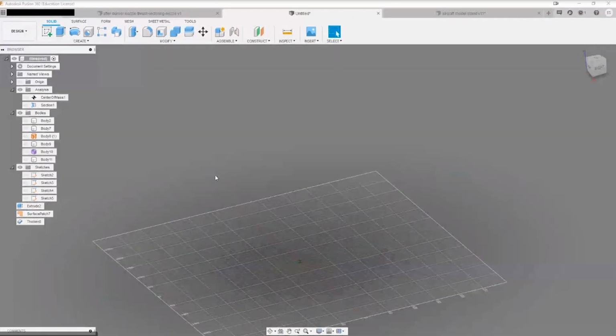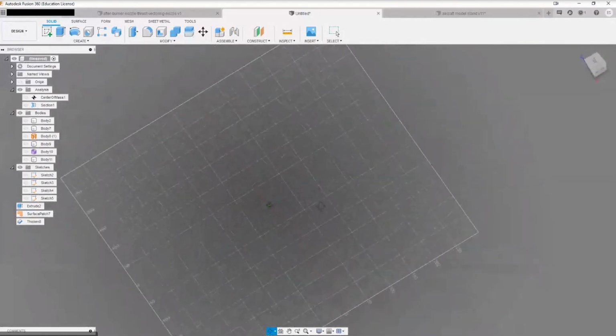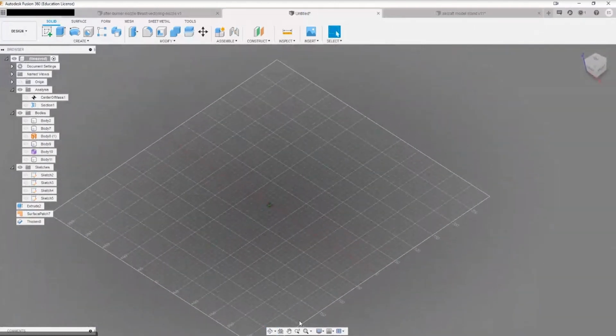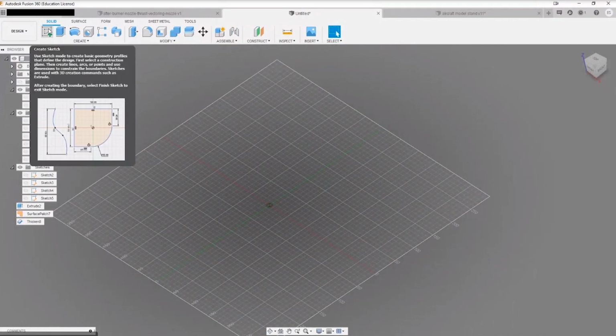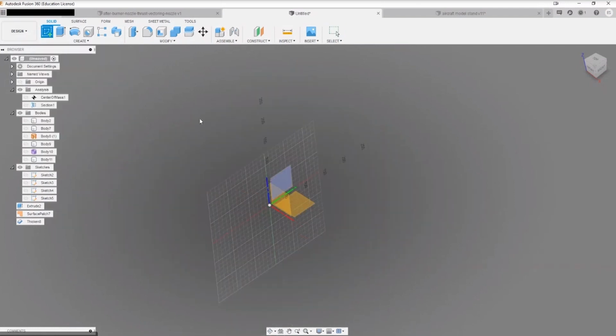Okay, so starting from the beginning, what I want to do is show you a couple of really important principles that are going to stop your sketches from messing up your ultimate 3D model, and a couple of other bits of advice. So if you go to create sketch, it's up to you which axes you want to work in. When you're creating larger assemblies, there's usually a convention that Z will always be up. So if the component's oriented up, you make sure you stick with that convention.